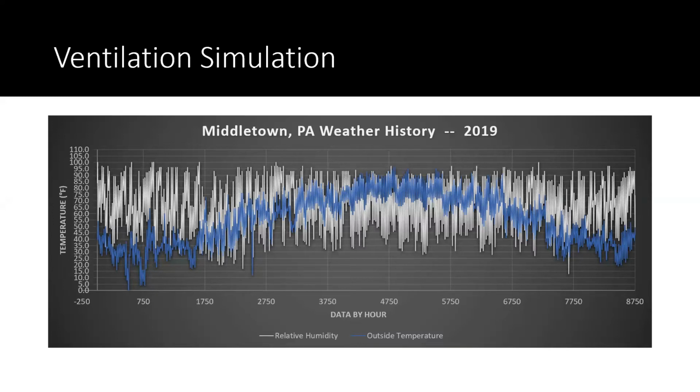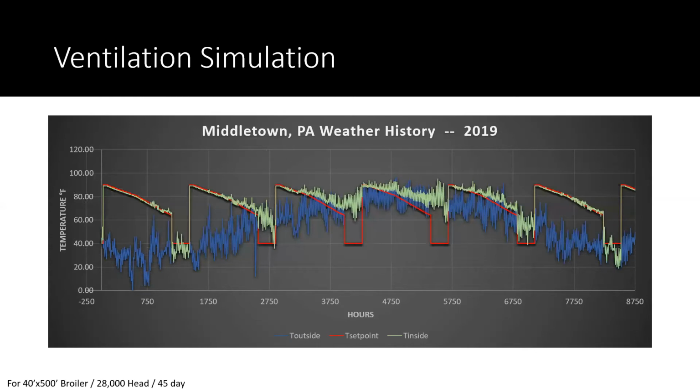In this case, we'll be looking at a broiler house, and even as the temperature increases in the barn, the sensible output changes. So how does that impact it? If we're adding supplemental heat, if we're adding evaporative cooling, and then even in the barn status, we have different age ranges that we're growing birds to. How does that impact it? And then static pressure, as we saw in the charts. Static pressure impacts the performance of the fans, controller set points, things like that.